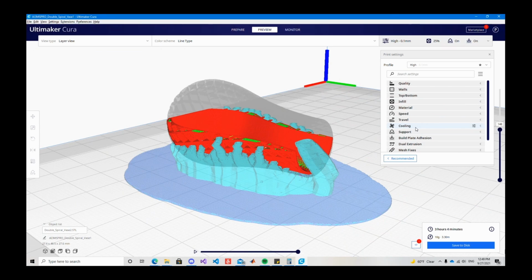Instead of cooling it maybe 20 to 30 seconds after it came out, it was cooling immediately, as soon as it came out of the extruder, so it wasn't sticking. I woke up to a completely destroyed 13-hour print, essentially. So that's also filament wasted, which means money wasted.